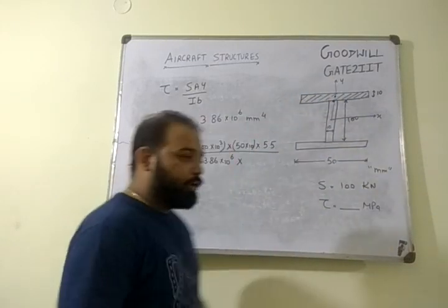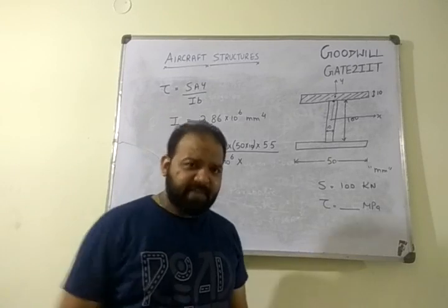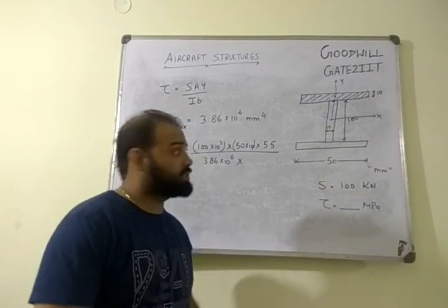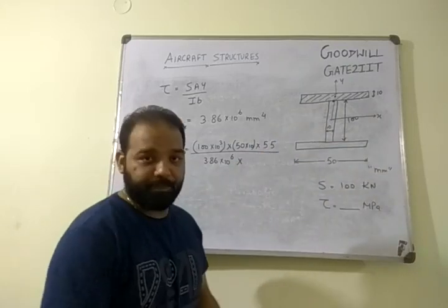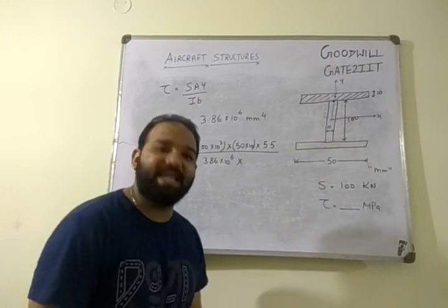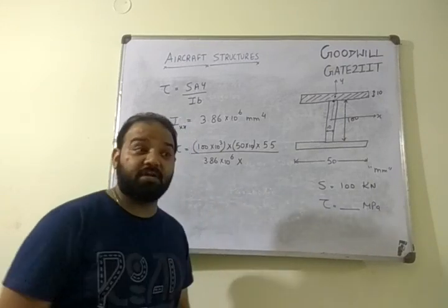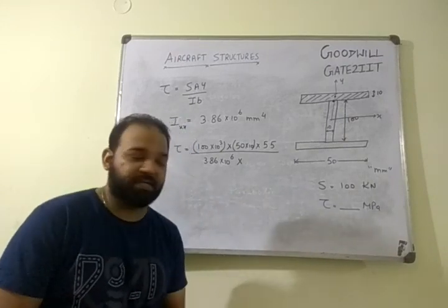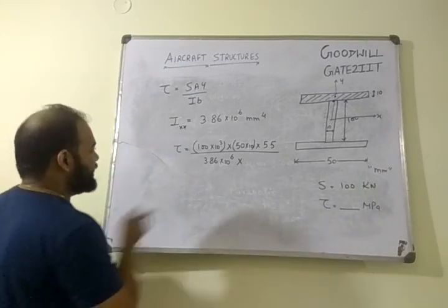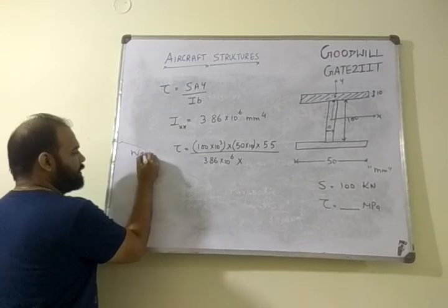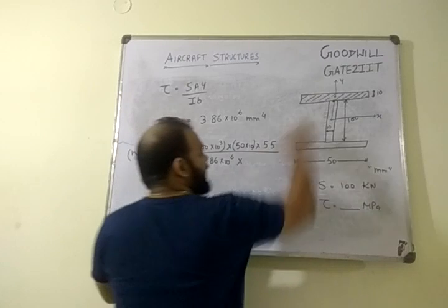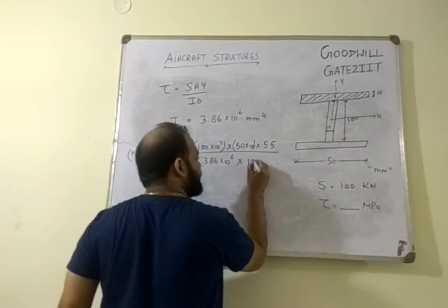What to solve? So in your exams or anywhere, the numerical can only be framed in such a way that: please calculate shear stresses at junction in web. Please calculate shear stresses at junction in flange. They cannot calculate shear stresses in junction if it is a combination of two different thicknesses. So wherever you want to calculate, that thickness should come here. Let's say for example, we are calculating in web center portion. So web thickness at this junction is 10, right? So 10 will come here.